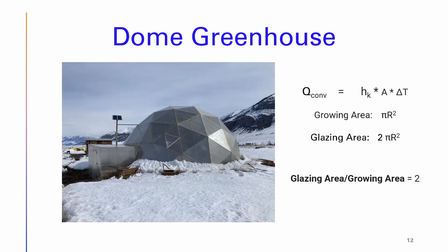Okay. So by insulating the north side, I'm saying build a greenhouse with polycarbonate glazing. No matter what exterior finish you use, whether it's metal or vinyl siding or whatever, there's a cost attached to it. And it's just so much easier to put on polycarbonate. It might be more expensive than some stuff, but the stuff I'm selling is the same price as your corrugated steel. So why not just use polycarbonate? It looks better, it's easier to install, and it provides R value. So just do that.